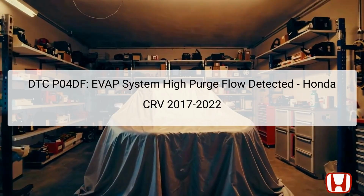The Diagnostic Trouble Code, DTC P04DF, indicates an issue with the engine's evaporative emission control system, specifically signaling a high purge flow detected from the EVAP system. EVAP stands for Evaporative Emission Control System, which captures and recirculates fuel vapors to prevent them from escaping to the atmosphere, thereby reducing pollution and enhancing fuel efficiency.